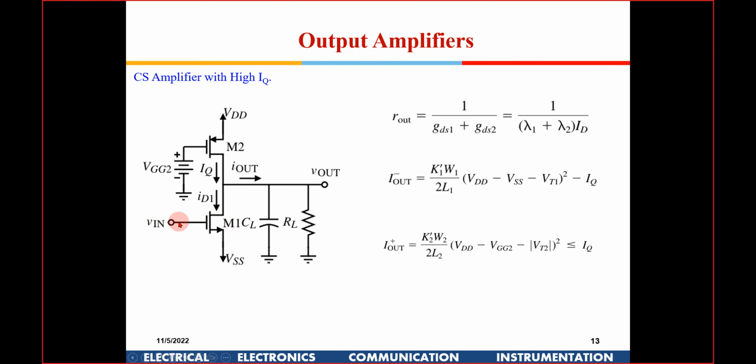The current on the input side is almost negligible because it is the gate, so there is no power here. Whereas at the output, almost the same voltage is available, but a large current can flow into the load resistance, and hence there is a power gain. So these are known as power amplifiers or output amplifiers.